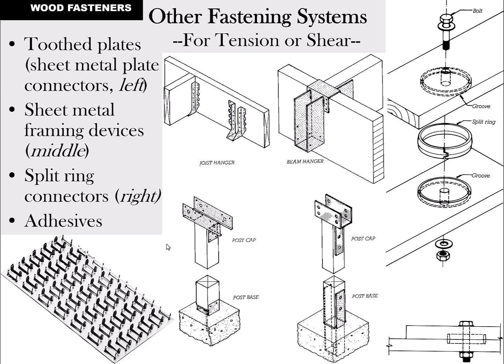That's a spring steel piece of steel that is just the right size for this auger that you augured out so that you can slip that in there between the two pieces. And it's kind of springy, so when you fit it in there, it's going to be tight in both. And so it's half in one board and half in the other. So when you then run that bolt through with a big heavy washer on each side, you can make an incredibly strong connection between two pieces of wood.